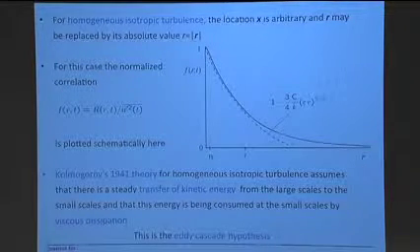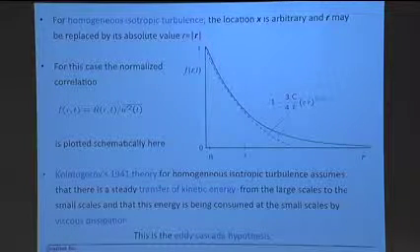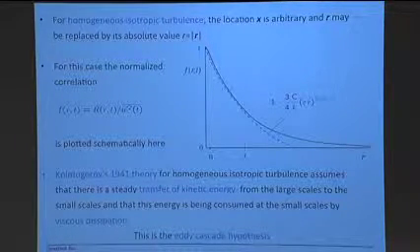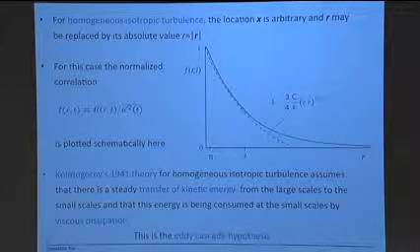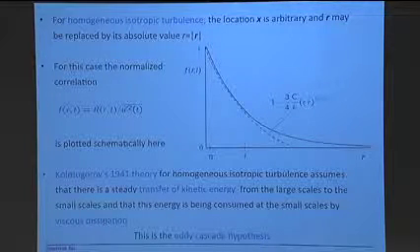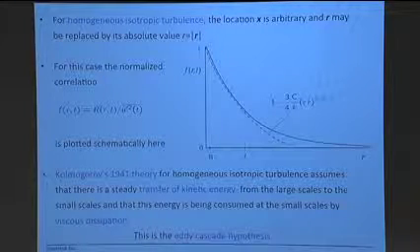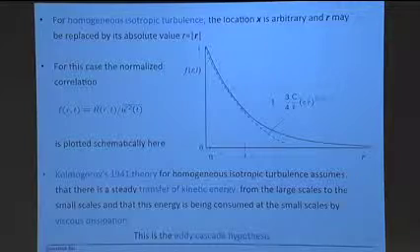And so what you do here, in order to define a length scale, is you just integrate over the whole area here and divide it by 1, and that basically tells you that would be a square, or a rectangle here, that has the same area as what's under this curve. And you say that's the so-called integral length. That's a measure for the largest correlation distance. And because it's defined with this integral, we call it the integral length.